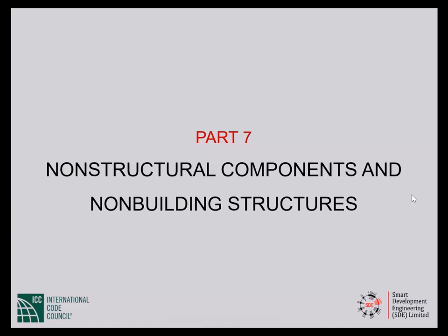Anyway, it should not make any difference unless you have a distinctly unsymmetrical building. Gravity loads are not going to contribute significantly to the lateral deflections. So what load combinations is not irrelevant, but it's kind of a non-issue.